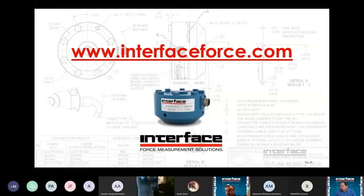Paul's asking for a 10 kN or a 2250 pound force application. Is that too much for a 2,000 pound load cell? Yes. It's above the calibrated range. You can't guarantee performance. Load cells will typically stay pretty linear 10% over capacity, but there's no guarantee on that. And again, you're starting to exercise the load cell into areas where we'd recommend you stay out.